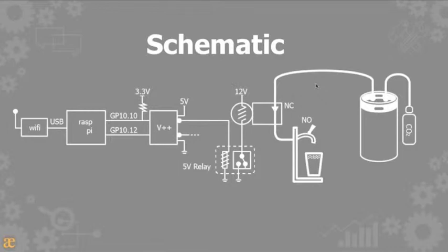We supported 2 beers. We actually only ended up pouring 1, and we could do up to 16 pretty easily. But most of the code I have in here is designed to support 2 different beers. Because ultimately what we're going to do is turn a valve on or off, we really just need 2 bits to do that. So for that we used 2 general purpose I/O pins. It looks like GP10 on the slide, but it's supposed to be GPIO. Those are general purpose I/O, and we're setting them both as outputs. So we used pin 10 and pin 12.